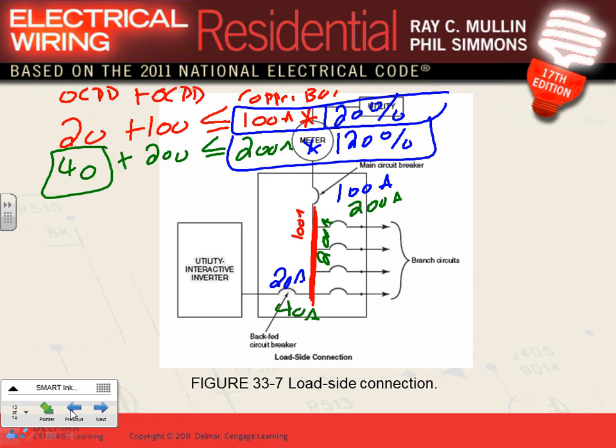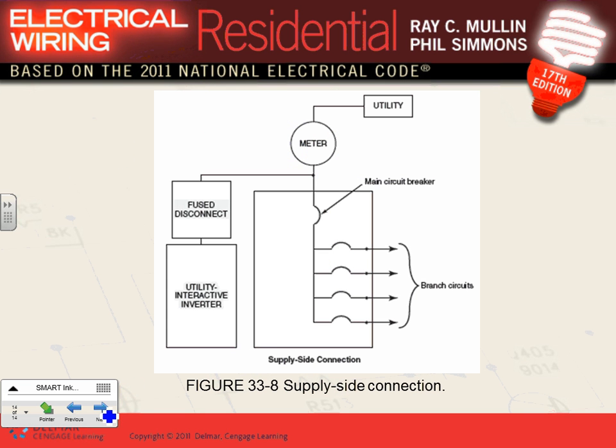So if you do, is this right then? Yeah. So that would be 120 equal or less. At least one of us is awake. So yeah, there's 100, it has to be equal or less than 120% of the bus bars. And you can do your math. Any question, guys, about this? So that's a limitation of that one. I'm glad you caught it, Joe. I thought you were sleeping, man.